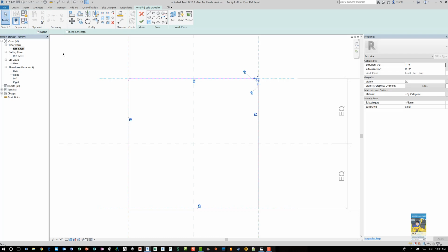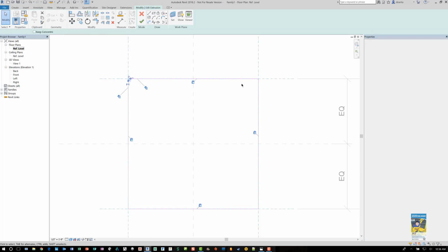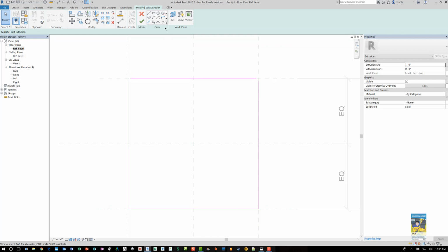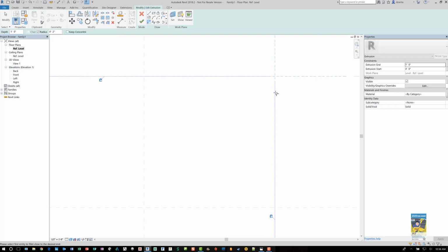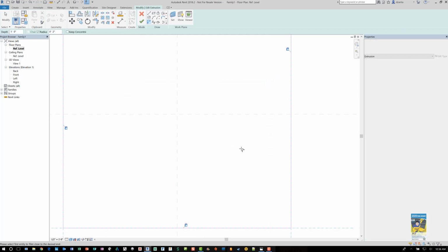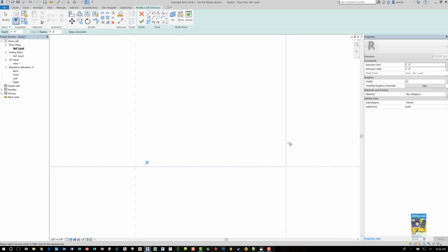So what I'm going to do is I'm going to delete those 2. And let's do that command again. And this time put in the radius of, say, 2 inches. Double the size. And again, locking the tangencies so it's a little easier. And the relationship of the endpoint of the lines with the endpoints of the arcs, they hold together nicely. This feature came out, I think, middle of 2017.